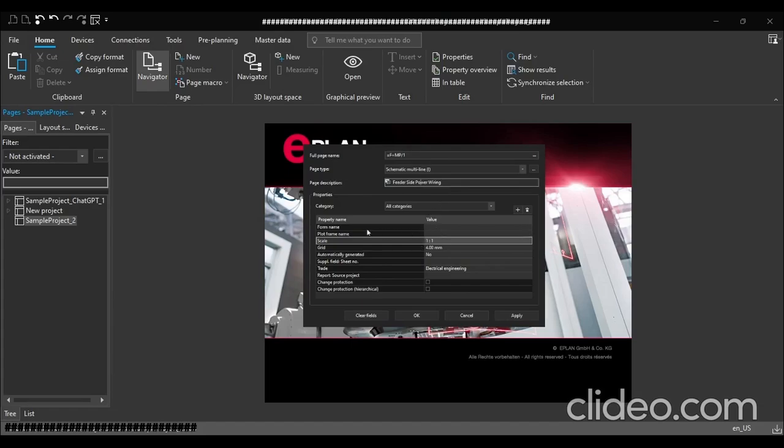Currently we do not have to disturb these properties. We can see here scale is 1:1, grid is 4 mm. We do not have to change the scale because all the wirings can be fit into this scale. When we go to graphical analysis, then we have to change the scale because the panel does not fit in this scale. Grid is 4 mm. Just say OK. What is the difference between these things?